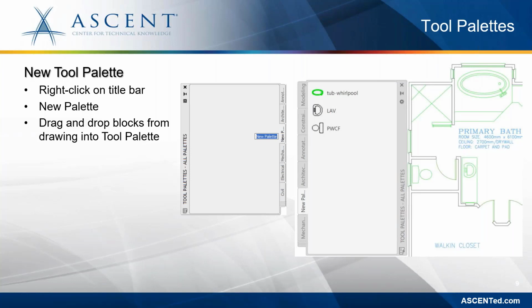As they are now saved in the tool palettes, you can then insert those blocks into any other drawing without having to define the block in that specific drawing, because all those blocks are already saved in the tool palettes, and the tool palettes are available in all the drawings. It does not matter whether you have saved those blocks in those drawings or not, because they are already saved in the tool palette.